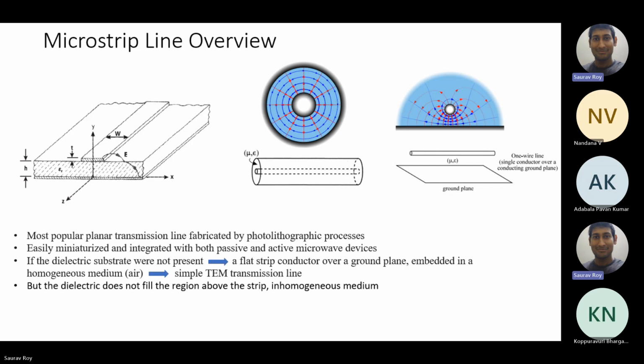So why are these all vital? Coaxial is used in many places. Nowadays in our lab also we use coaxial line. It is connected for power transmission because mostly it has a 50 ohm impedance, matched to all the antennas or circuits that we'll be using.